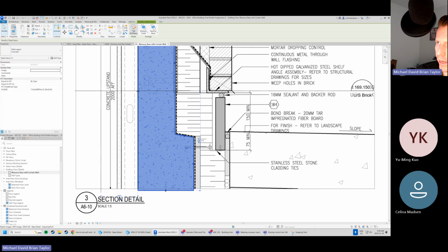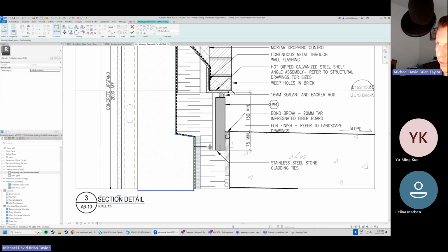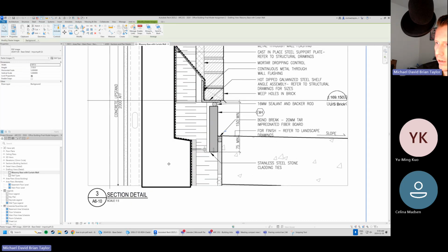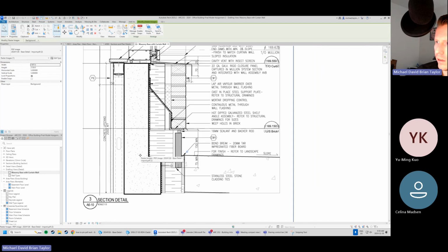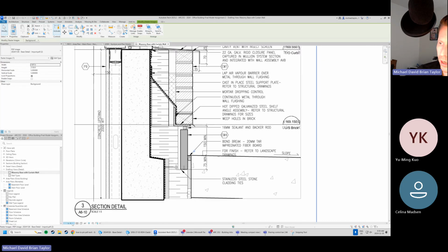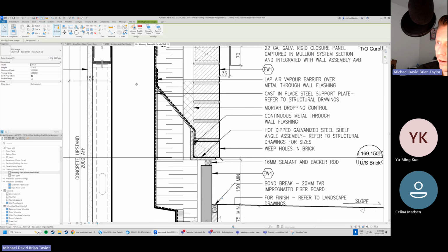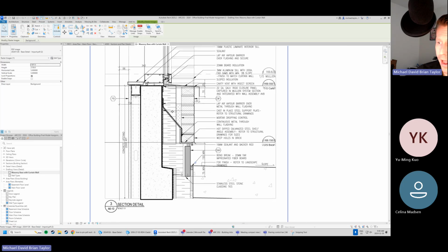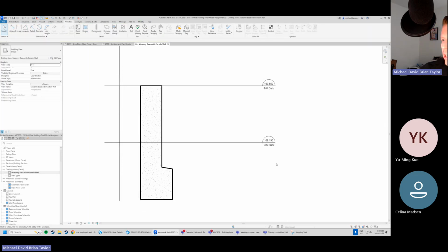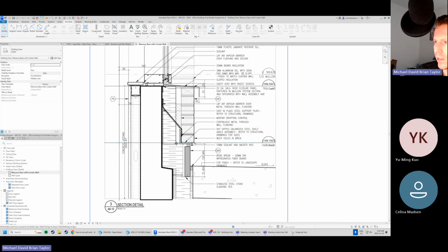If I want to come back in here and edit this, maybe I want a little thicker line here. I can actually make this wide lines. Check mark again. Nice, beefy concrete. So you can see here the scale for our hatch is also coming into effect. And I just right click here and hide this in the view, just so you can see this is actually what's in our drawing. We've just drawn the concrete. That's it.